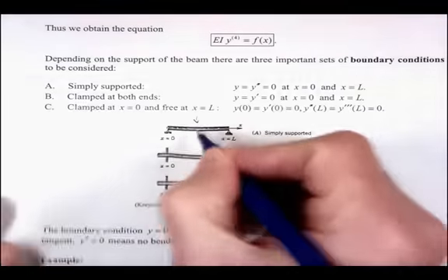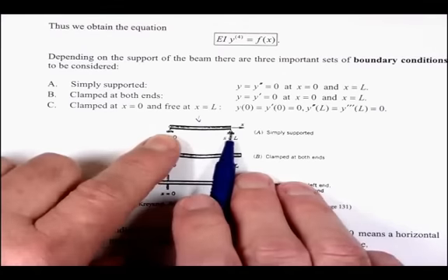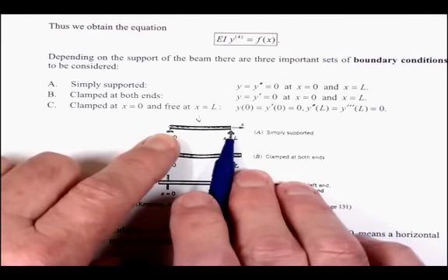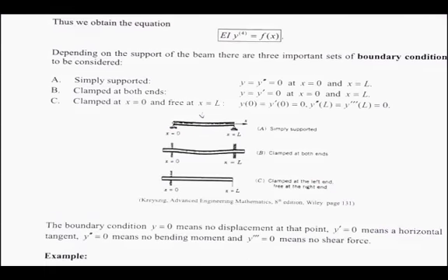Now you see there's even a slight assumption built in here, because technically, if these bearing points were right on the extreme very end, as soon as you put any weight down in the middle and the beam bent a little bit, what would happen? It would fall through, because the bending of the beam, you haven't lengthened the beam, means it must have got shorter in a horizontal sense.